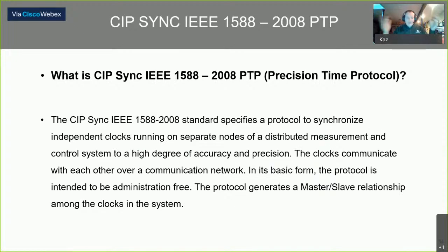So there's some handshaking involved, and that allows the drive to close the loop with the PLC. The PLC can say, I want you to be at position X at time X, and then the drive can say, okay, position X, time X, I will meet you there, and then they close that loop, and everybody's happy. That's how we get to do motion over Ethernet, with this 1588 precision time protocol.